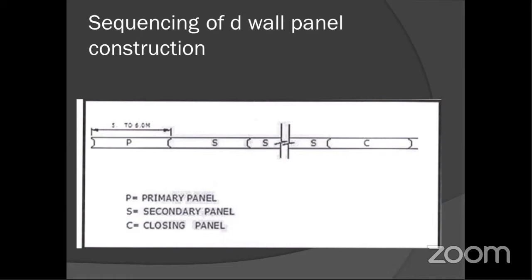We should be more conscious about these things, because if the stop ends or waterproofing material are not placed properly, it is going to affect our work later when we start the further works, like excavations. There will be some water leakage and all.